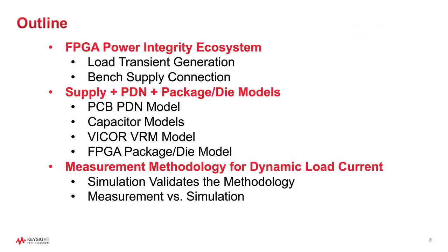The next step is to determine the types of models needed for simulating the power integrity ecosystem for the VCC-INT power rail. Models are needed for the PCB, the decoupling capacitors, the bench supply with Vicor current multiplier, and the load's package die model.